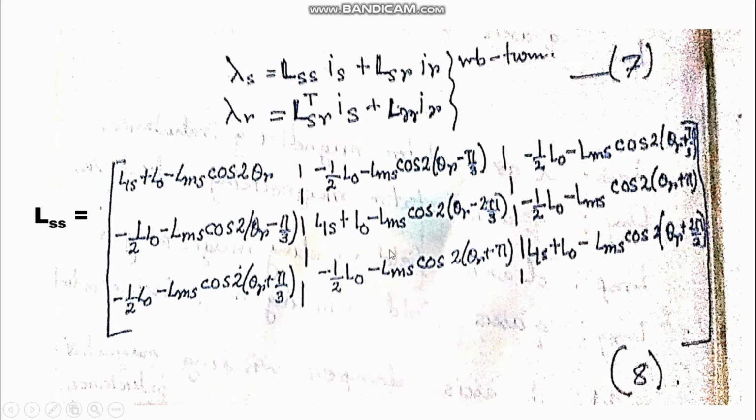Here again you can ask me why LSS, and I would like to help you recall the fact that although the stator winding has a smooth cylinder inner periphery, inside that hollow cylinder you are moving an iron structure, and that causes an uneven, time varying air gap inside your machine, and that is how you get different values of the self inductance LSS.